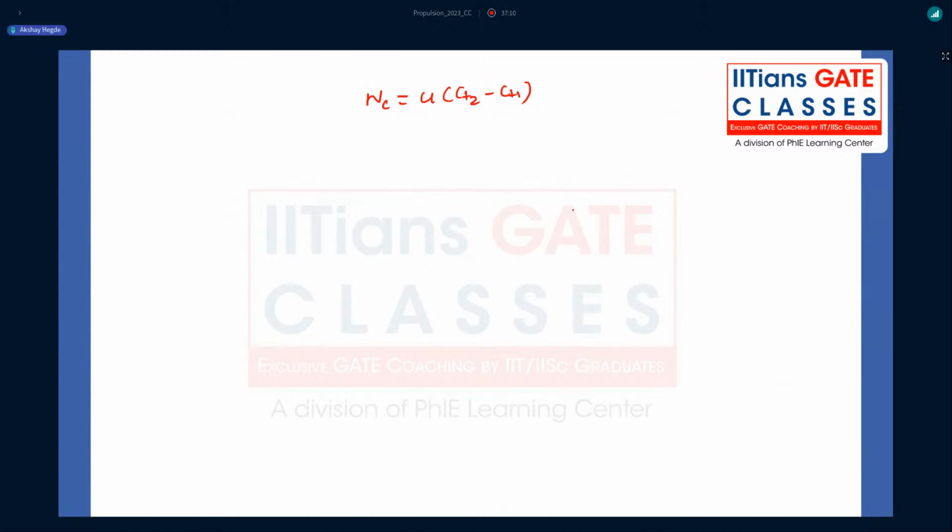So now we have to calculate what these values are. If I just draw the entry velocity Pythagorean triplet, considering C1, alpha 1, Ca, Ct1, I know alpha 1 and I know Ca, so I can calculate Ct1.